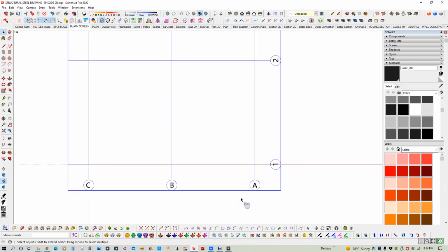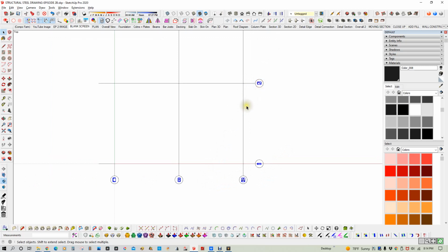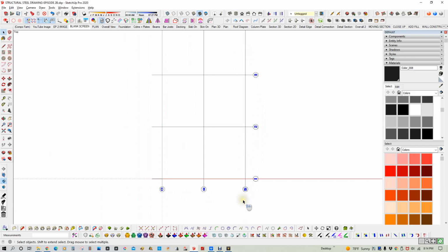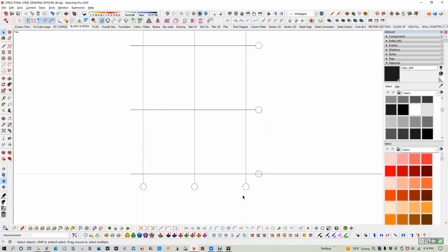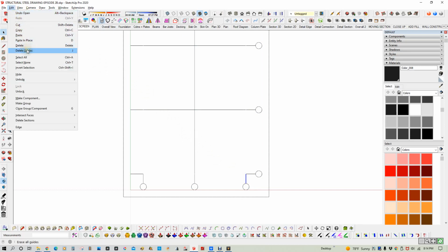Okay, so we have everything except for the numbers, it looks like, in that group that we want for the grid. And I think I'm going to put them in there. And I'll show you this nifty little trick. It's not hard to put things on the wrong tag. So select them all, hit Control X, which is cut. Then get into this and click on the grid and pick Edit, Paste in Place. And for me, I've actually made a shortcut for that as well, D, because I use this quite a bit. So I'm just going to click on that.